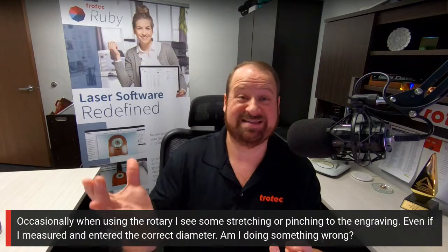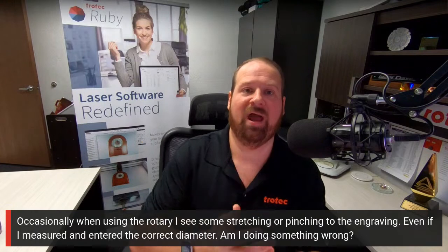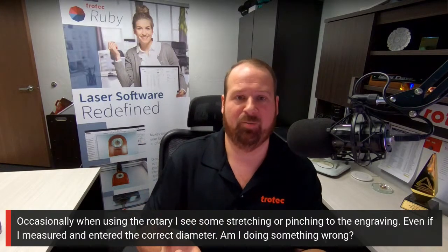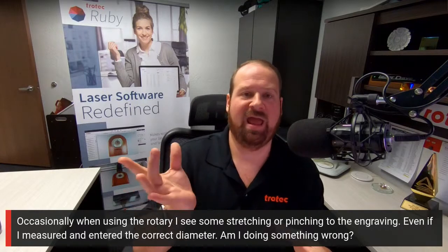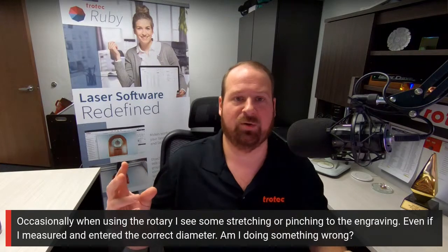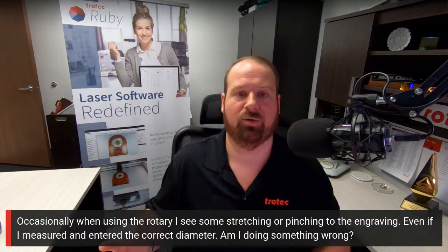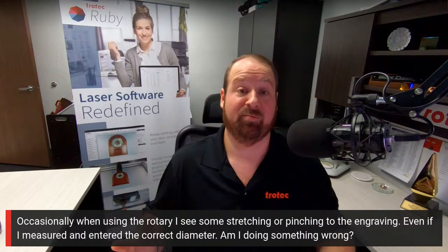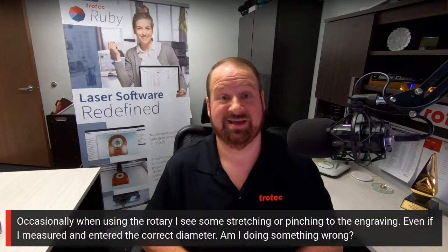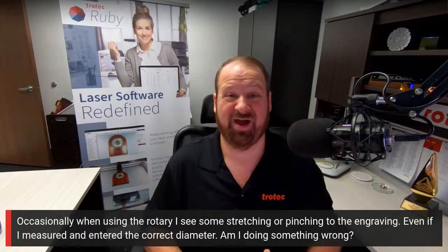Two, there's a taper on your graphic or on your actual tumbler, for example, and there's only one diameter put in. So if you put it in at one diameter and the engraving tends to go down an angled tumbler, or maybe something like a martini glass, that diameter is going to change drastically. And when it changes, it's going to skew, stretch, and modify how your graphic looks.